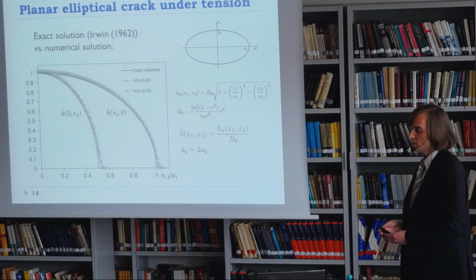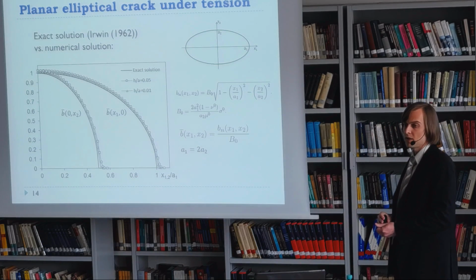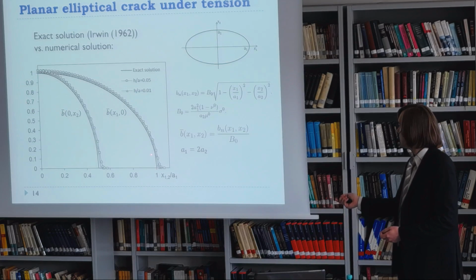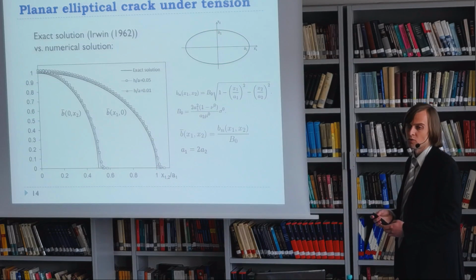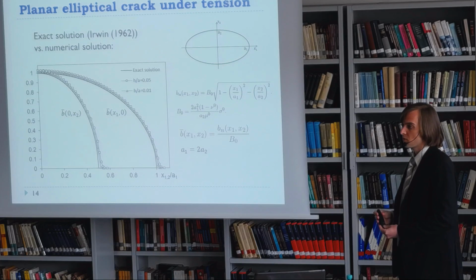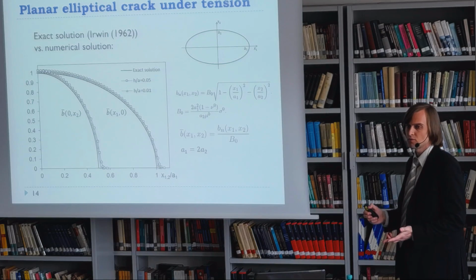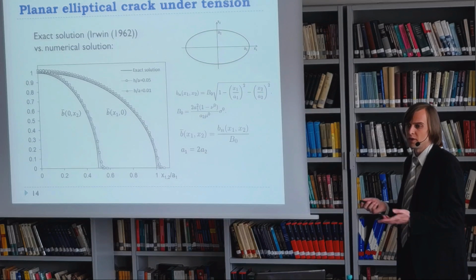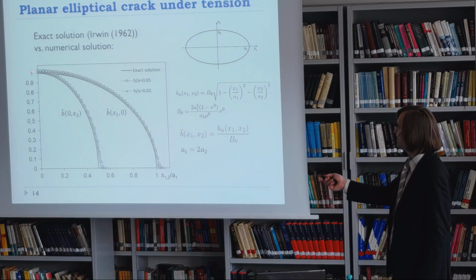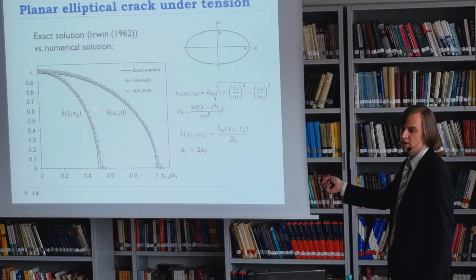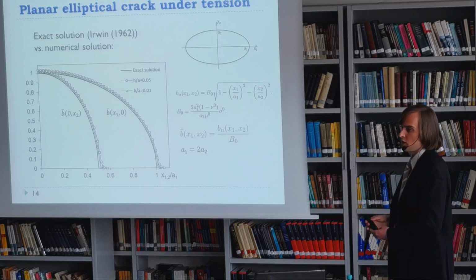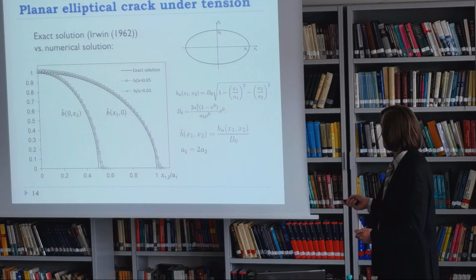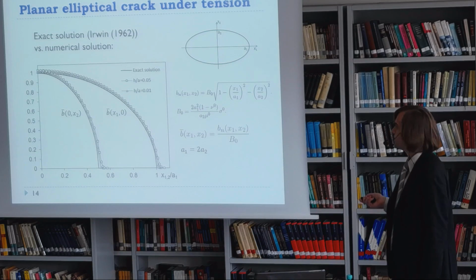So the main issue of the numerical method is that the values near the edges are not reliable. So we may discard them. Of course, for example, if you're going to calculate the compliance contribution of a crack, it won't be a major issue because we mainly need the crack opening here. But for the calculation of the stress intensity factor, yes, it would present an issue. Let us see how to treat it.